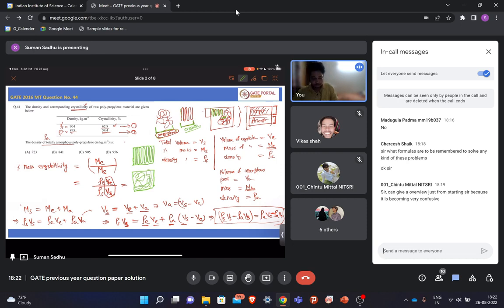Now you can see from these two schematics whose density is higher, the totally crystalline polymer or the amorphous polymer. You can just look at the schematic and get an idea that here it is very closely spaced, and it is arranged in a regular fashion, and the spacing is also very small.